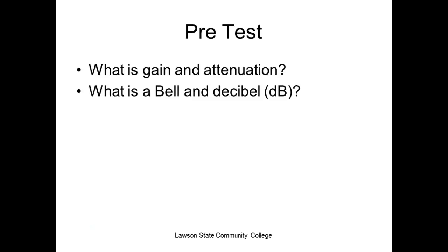They don't. You can go out there all day long and try to turn the volume on your radio with your battery off, and you don't hear anything. So you got to get that big battery or that big DC power source in there. And all an amplifier does is manage that power. So when you say you get more power out than you put in, then what you put into it is what you're trying to amplify. The power that you get from your amplifier comes from your power supply, right? So what's attenuation?